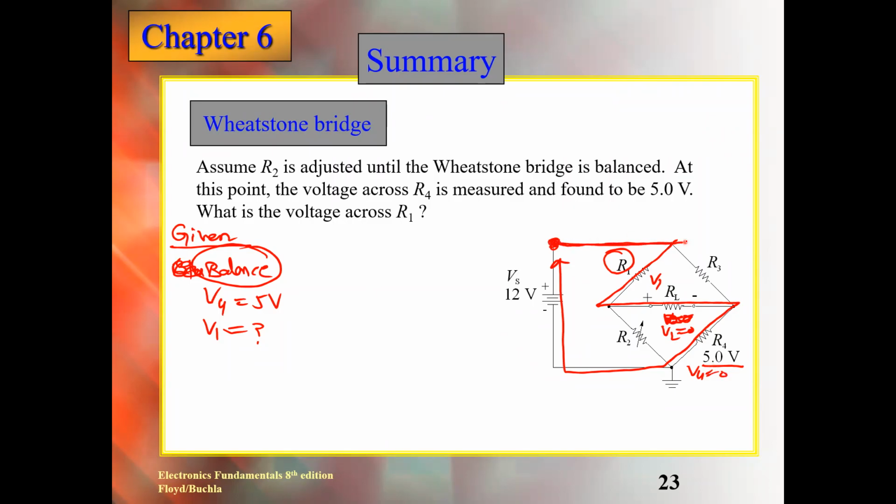When you are going from here to here, which voltage is coming here? Again, as I said, the traveling path is marked like that always. So you can apply here. What is this? V1. Then what is the sign when you reach here first? Plus. VL positive, plus. How much is it? 5. V4 is equal to Vs. What is V1 now? V1 will be Vs minus VL minus V4.